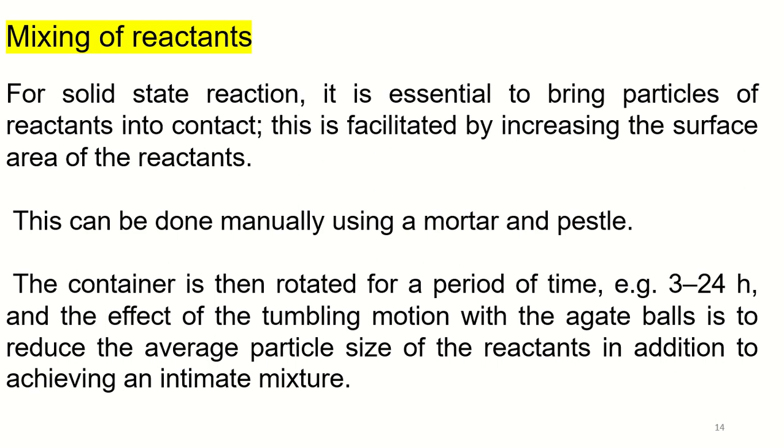While the mixing and milling processes are carried out rapidly and effectively, there is a danger of contamination from the milling media. To facilitate mixing by whatever method, a liquid such as water or an organic liquid is often added and then needs to be removed by drying at the end of the mixing stage.